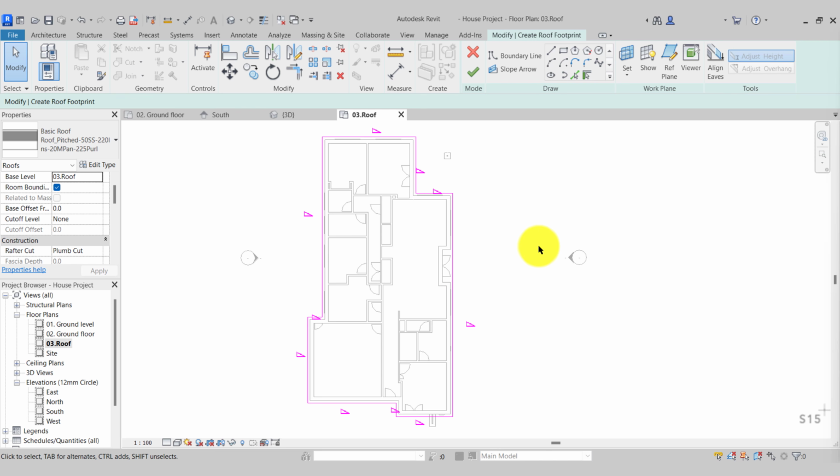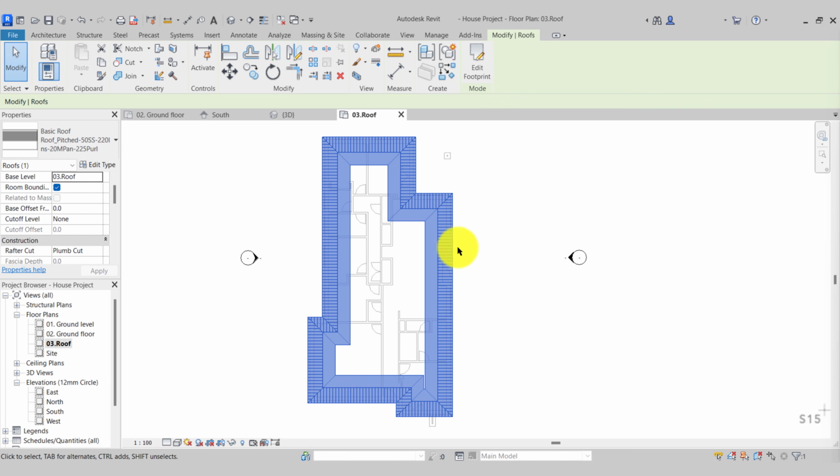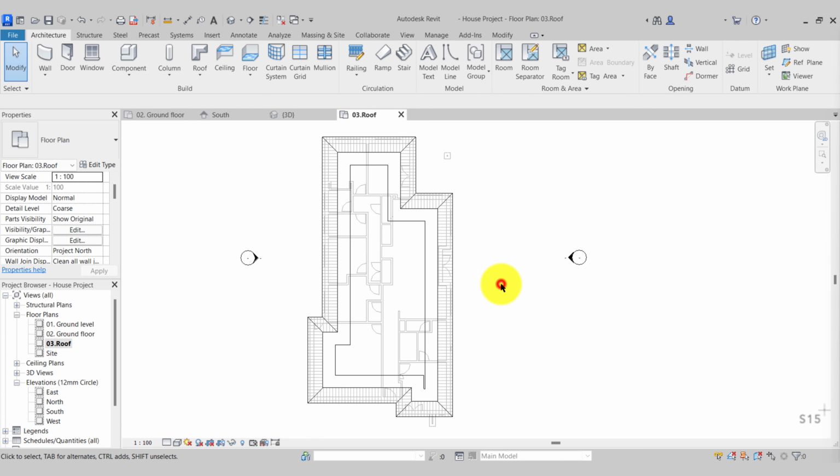My advice is that you should always just create the boundary, green tick to finish. If there are no issues, the roof will be placed. But there can be some issues in creating the boundary. If you spend a lot of time working up your roof by changing the slope and so on, and then you go to hit the green tick, the roof will not build itself, so you've just wasted some time. So my advice is to always just place the boundary, green tick to finish, and then we can go back into the editor. We know the roof has been placed and we can continue.